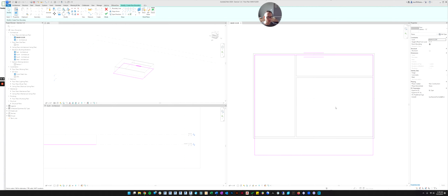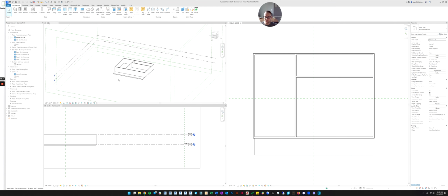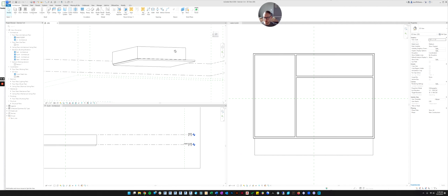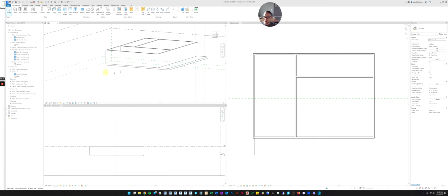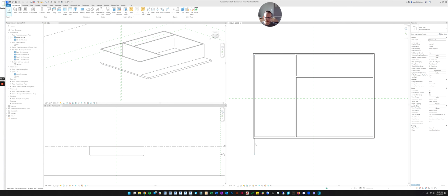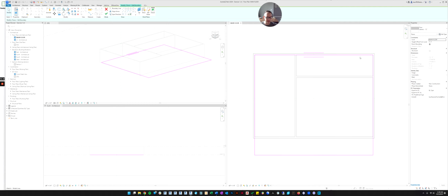And when we have the floor the way we want it, we're going to finish the sketch. So we have to come up here and hit finish, the little check mark, and now it builds the floor. Do you see how it's added the floor in? But maybe we don't like how it did it. So let's go back. We can highlight the floor and you can come up here where it says edit boundary. You can click that and it'll take you back into the sketch.